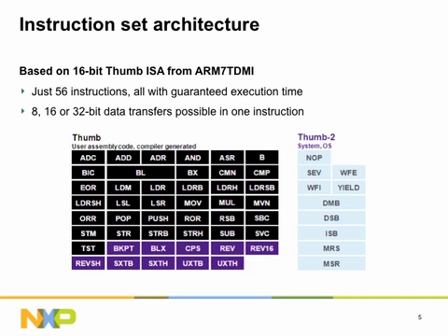Let us start with an understanding of the Cortex-M0 instruction set. The Cortex-M0 is a RISC or Reduced Instruction Set Computer architecture based on the ARM Thumb concept. The complete instruction set for the Cortex-M0 can be seen in this diagram. Almost all of the Cortex-M0 instructions are 16 bits in length, but operate on 32-bit registers and 32-bit data paths. The only 32-bit instruction used in application code is the BL or branch with link instruction.